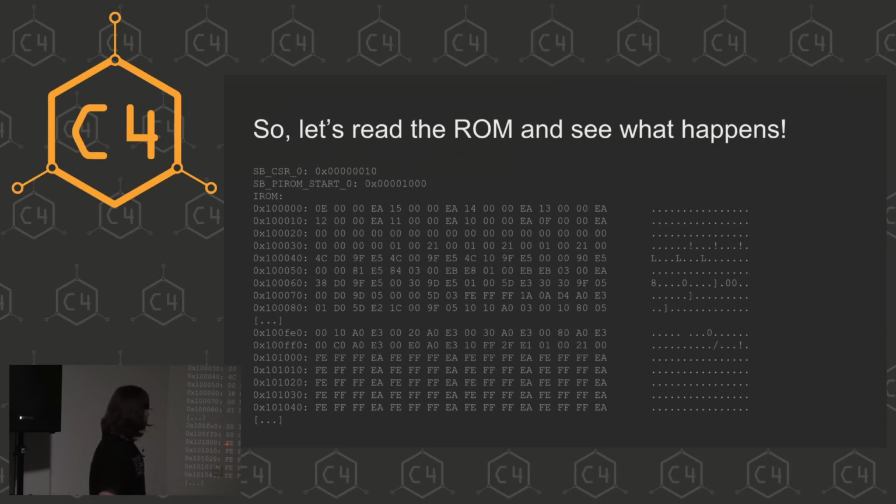But here at 0x1000, we just get some weird stuff back. Seemingly random-looking stuff, but always the same pattern. And if you disassemble this, it's the opcode for jump to address 0. Why? No idea. I never tried to jump to address 0. Maybe this chip resets or whatever. So if you try to execute this code here after the boot ROM is locked, it does whatever, but it's not going to execute the ROM again. And also, we can't read it.